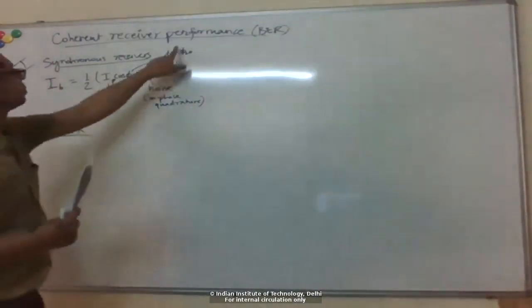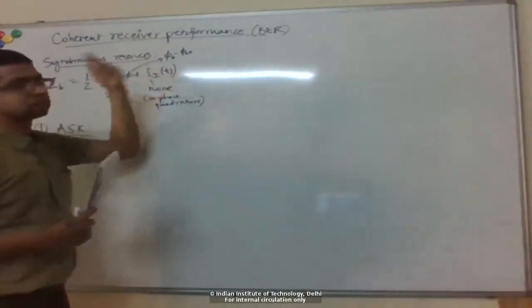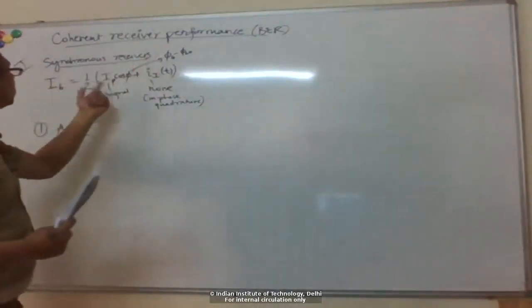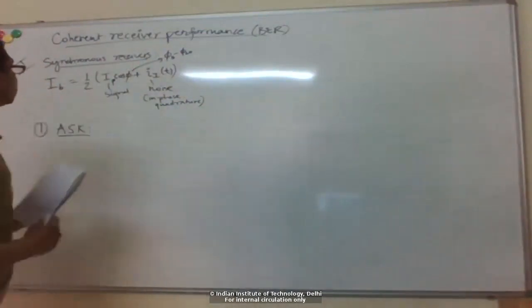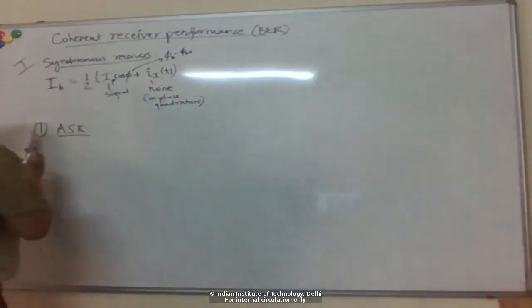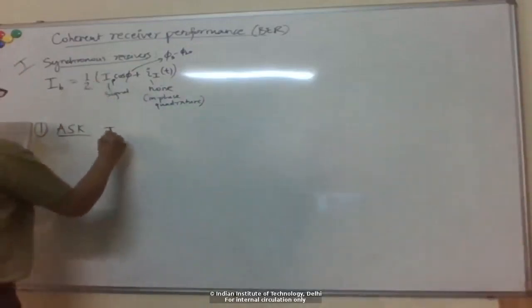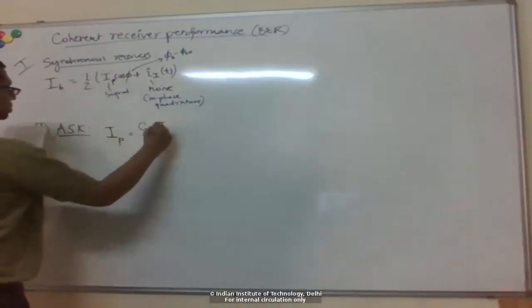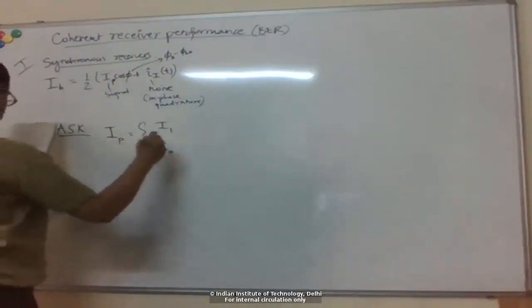So for ASK, of course, the phase is not important, right? We encode information in the amplitude, so only the I component matters here.